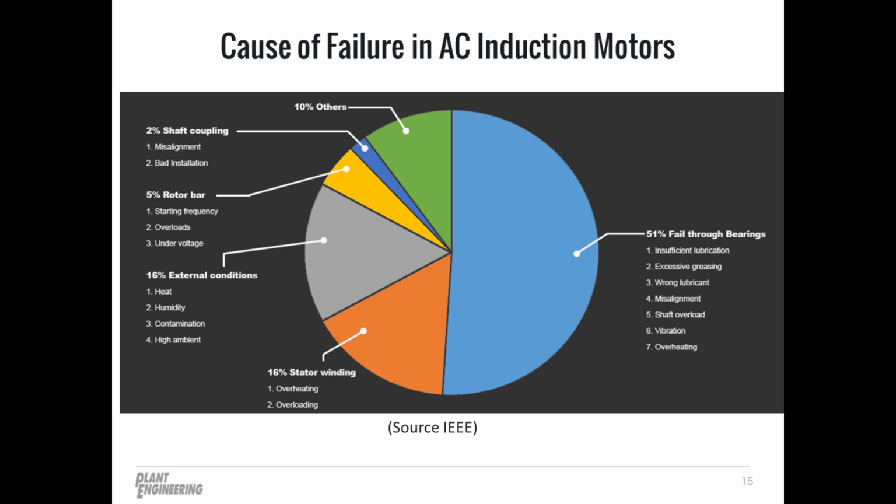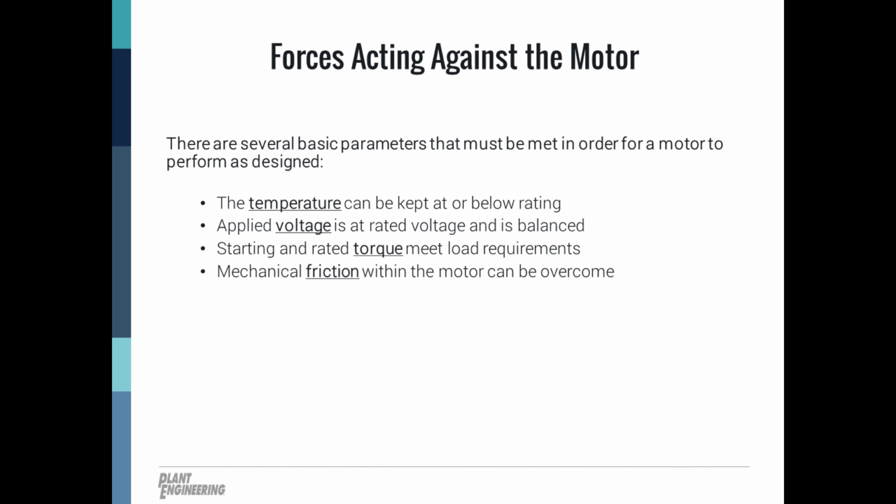When you match a motor to an application, it will typically be matched based on nameplate speed and horsepower, target output. In many applications, the motor may experience short-term overloads, and due to this, most motors would be marked with a service factor. The service factor could be found on the motor nameplate or in the product literature. Most motors would be equipped with a service factor greater than 1.0, which means they could safely operate above rated load for short periods of time. So definitely keep in mind, limiting premature failures. Verify your nameplate service factor if you suspect some overload may be occurring.